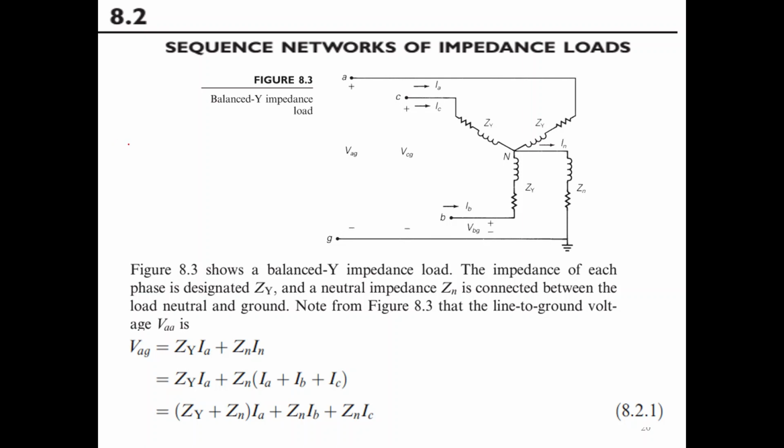You can see that V phase is A times Vs. So this is the transformation matrix. You can change the Vs into Vp. But normally we know the Vp, or phase quantity, and we are interested to find the Vs. So Vs is simply the inverse of A times Vp. And remember the identity of the A inverse: it will come with the factor 1/3 in front.